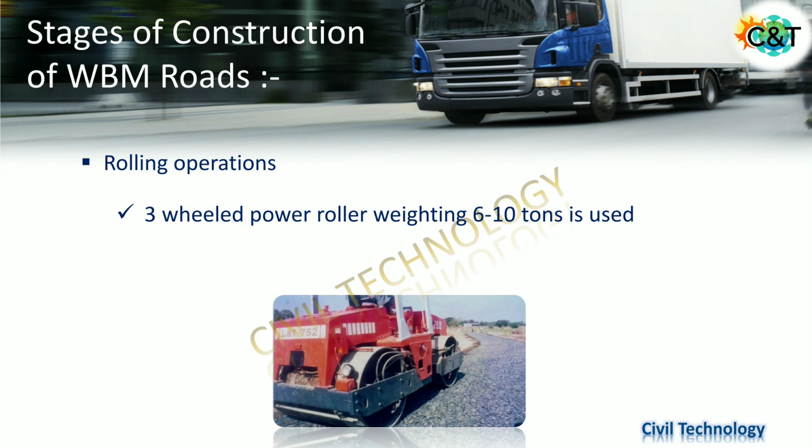For this, a skilled labor force is needed for driving the rollers, because if any fault happens in the rolling operation, then it causes the formation of corrugations, sometimes unequal finish of the road surface, wearing of the roads and all that. Because of this, your road will break within very few months after construction. So it clearly indicates your rolling operation had some fault, and it very much affects your road construction cost. So please take care, skilled labor is needed for this operation.